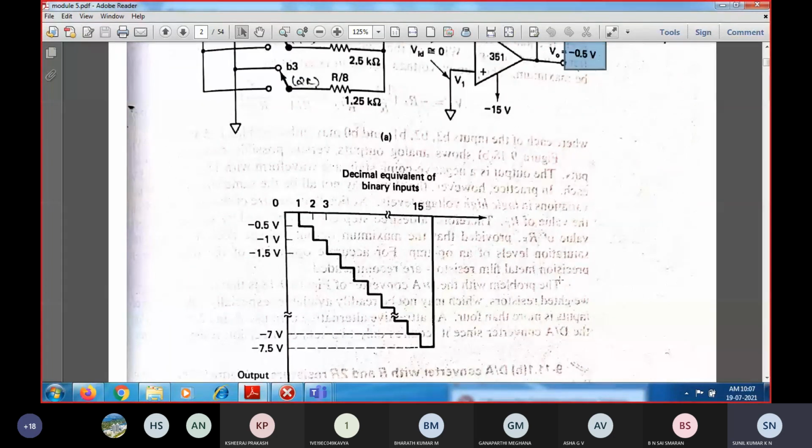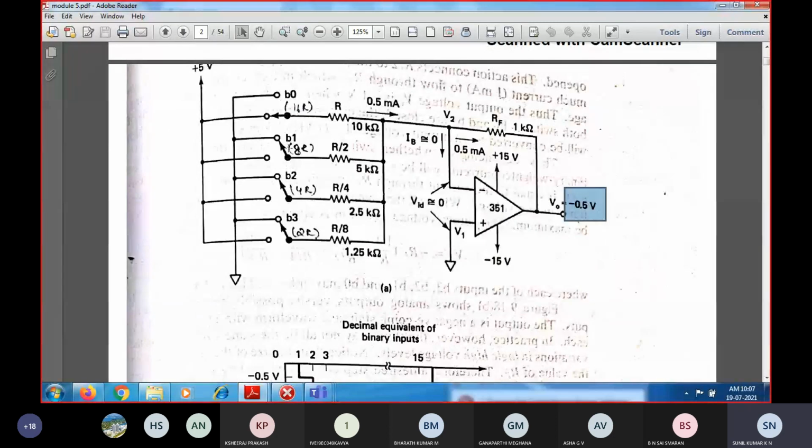For this, instead of connecting bit by bit positions, we can connect a 7493 counter, which is a 4-bit binary counter. Based on that binary counter, it is going to count from all zeros to all ones. In that way it connects each bit position so that we get all the 16 possible outputs.